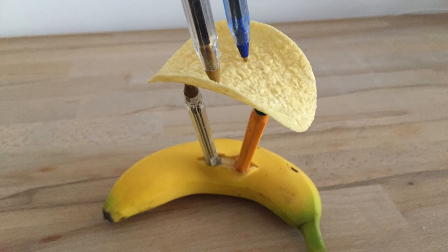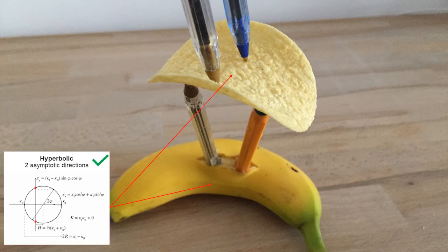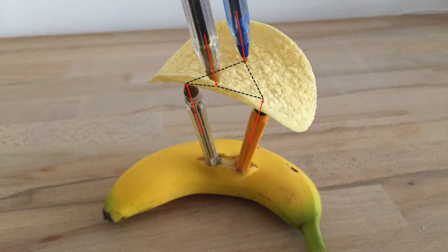We would like to end this presentation with some remarks about our interest in asymptotic directions. And this applies not only to minimal surfaces, but to any surface with negative Gaussian curvature, which, as mentioned before, can be considered approximately minimal. So, of the objects in this picture, it applies to the entire hyperbolic paraboloid-shaped crisp and parts of the banana with negative Gaussian curvature. If the points are chosen carefully so that we can find asymptotic curves running between the loading points and the support points, the loads will be transferred through the surface as a force couple along the asymptotic curves. The rest of the surface will, in theory, remain stress-free.